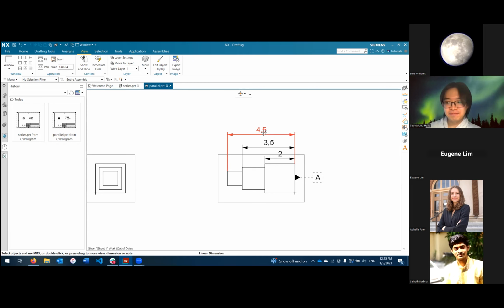So generally what machinists will try to do, if there is no nominal given, is go for the upper dimension and stay close to that, so they have margin in case they need to cut more material off. And so with limit dimensioning, generally what you're going to receive in return is a part that is closer to the maximum dimension rather than somewhere in the middle. That's just to make the machinist's job easier to hit that tolerance with margin.